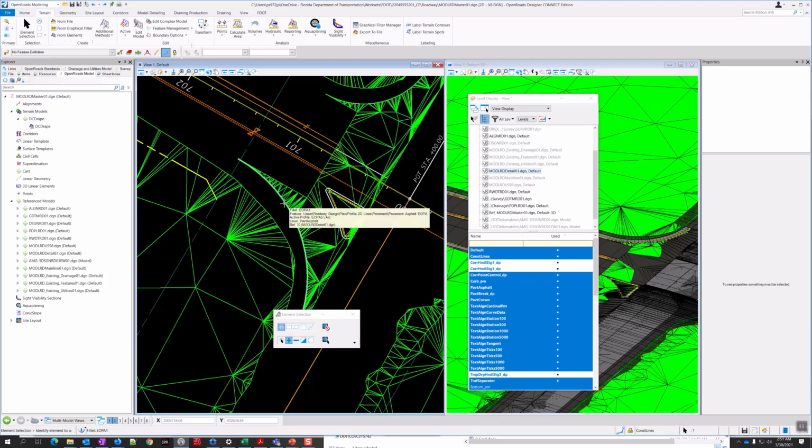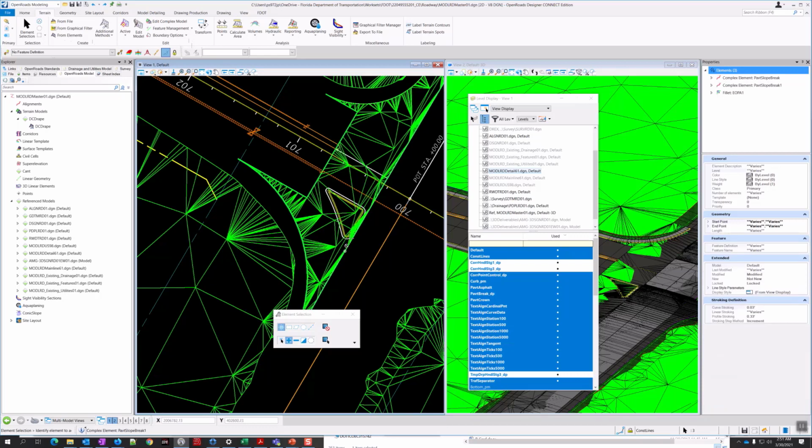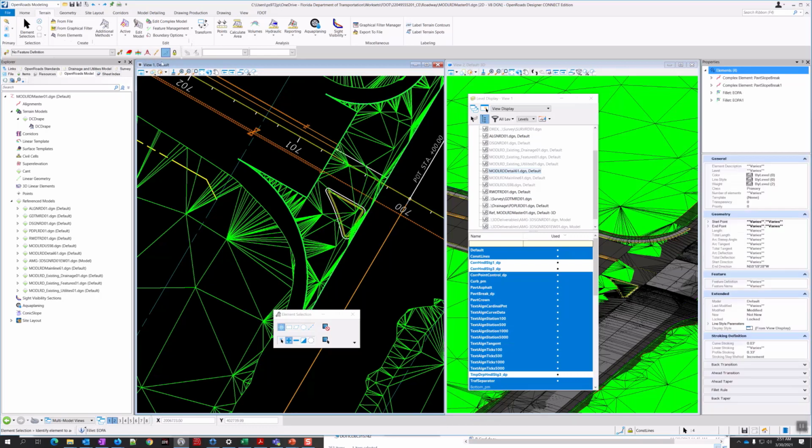Oops, make my selection set first. 4 lines. Change feature type. So this time what I'm going to do is the drape void. The intent of the drape options is that it drops it down to the level of that surface. So I've got these lines, I got these profiles, so we just need to lower them to cut right on that surface. And yes, we do want to create a void.